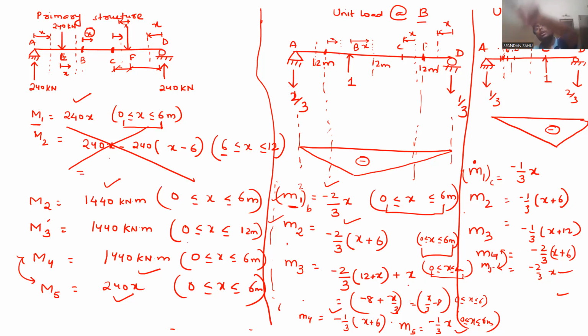Now, at C, you have to calculate the displacement due to B. So wherever you have to calculate the displacement, you have to put a unit load, because initially in that main structure there was some CY reaction. CY we don't know. So just put one unit load, calculate M1C, M2C, M3C, M4C, M5C. Done. Then you have M of B's and M of C's.